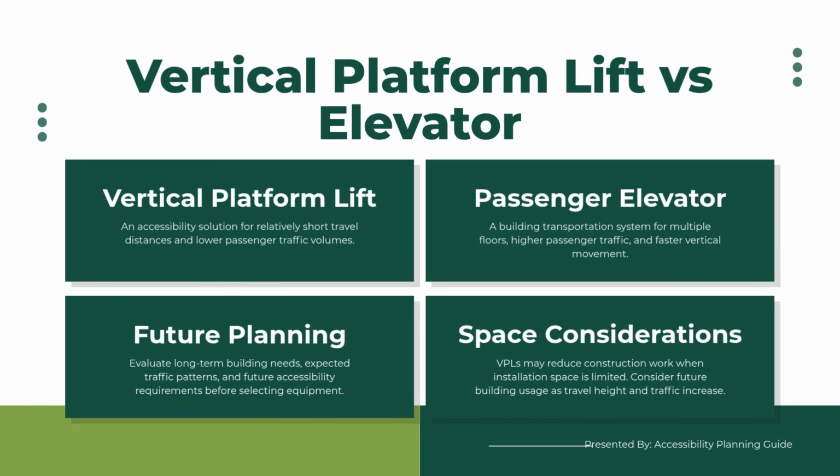8. Modernization or complete replacement. Some existing buildings already have elevators. In that case, the question may be whether the system should be modernized or completely replaced. Modernization can involve upgrading controllers, traction machines, door operators, safety systems, or suspension components. This can improve ride quality, reliability, safety performance, and diagnostic capability.